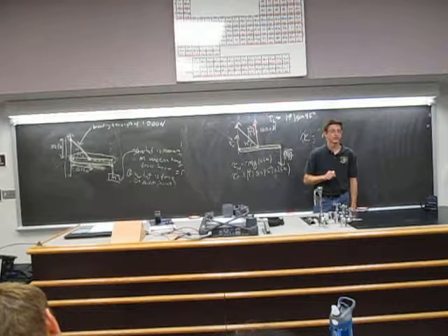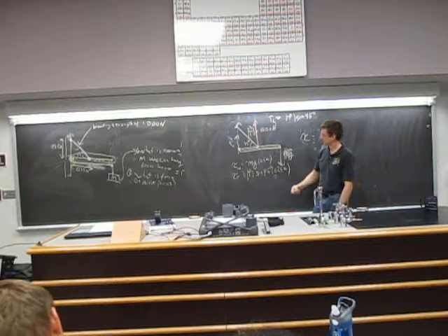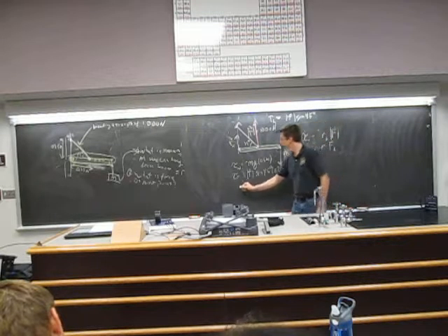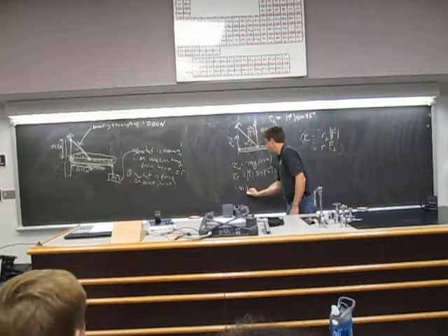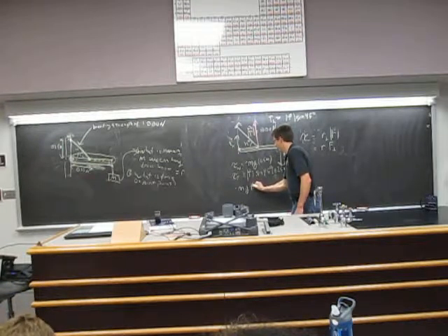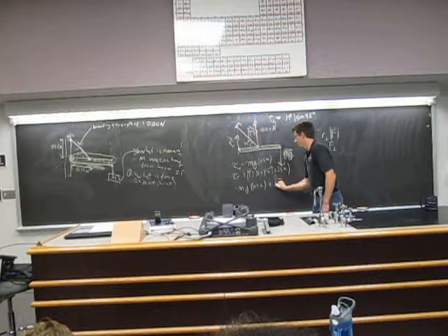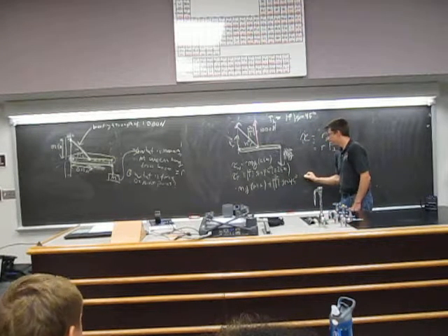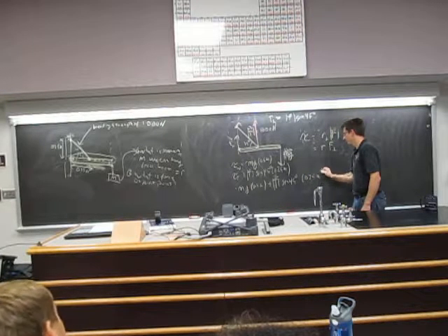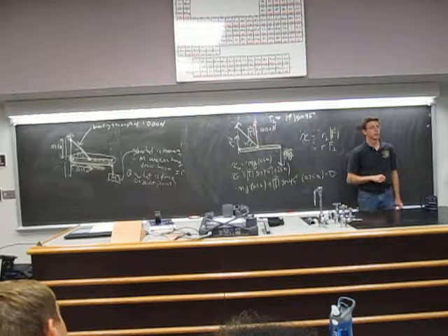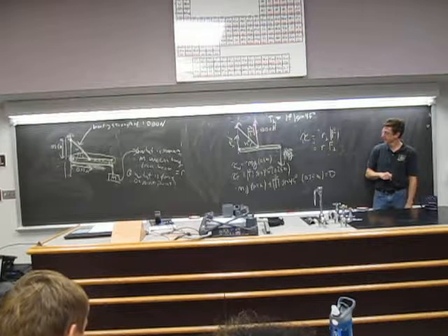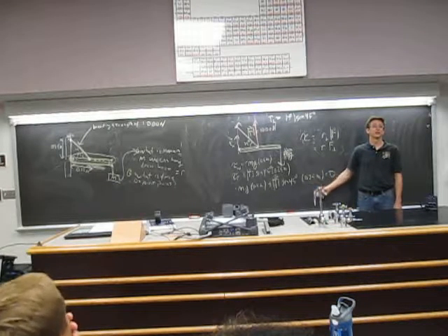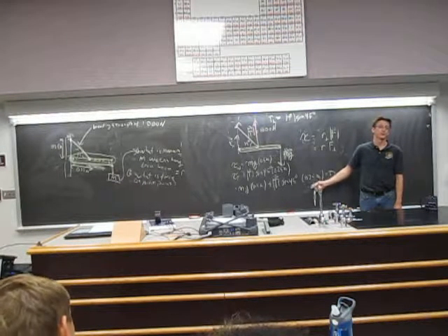And is that a positive torque? Yes, it is. All right, so these have to sum to zero, right? So I can do minus mg times 0.5 meters plus magnitude of tension force times sine of 45 degrees times 0.25 meters, and that's equal to 0. The sum of the torques is 0 in equilibrium. So you're adding them together there? Yep, I add them together and set the result equal to 0. That's my condition for equilibrium.